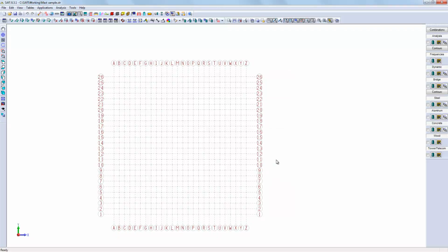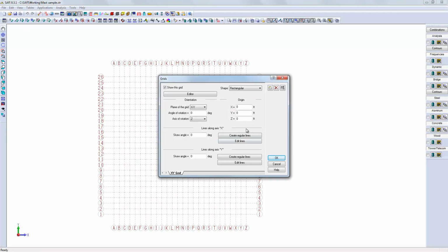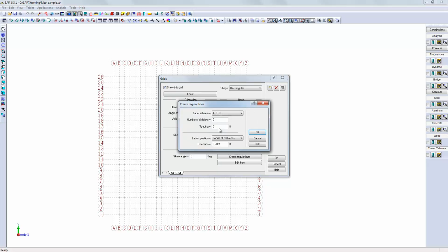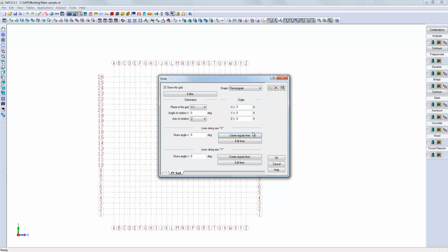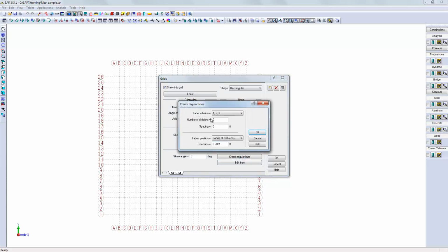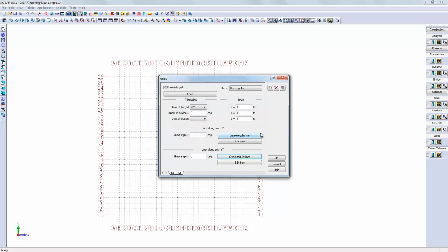There are multiple ways to create the structure elements such as joints and the members. In this example, we will use the grid technique. We will specify a given spacing between the lines in the X direction and in the Y direction. The spacing in the X direction will be 7 feet and the spacing in the Y direction will be 3 feet. The grid orientation will be in the XZ plane.